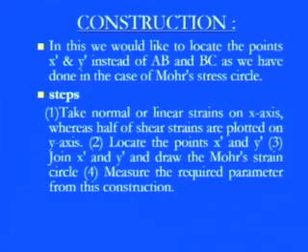So once you have the Mohr strain circle on this point, you simply get the center point, and the center point will give you exactly the locations of those other points. Once you do that, you see a horizontal line on the strain axis, which is nothing but the direct strain component, and you have this x dash y dash joining line. So now measure that angle.